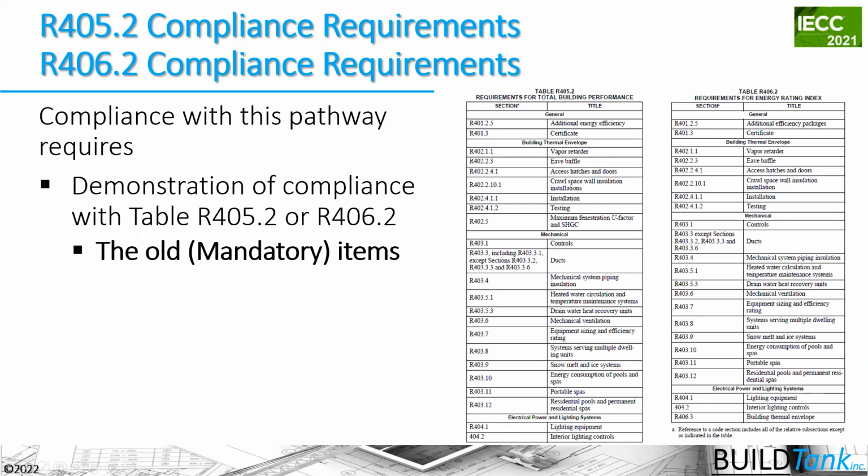So now it's crystal clear that attic eave baffles are required regardless of the compliance option, because the words prescriptive and mandatory have been removed from the code. It's just a requirement. And if it's applicable to the house that you're building, meaning that you're doing a ventilated attic, then you have to install that attic eave baffle. And so this is just a reminder that in these different sections of the code, there are requirements that you need to do, regardless, again, of that compliance option.